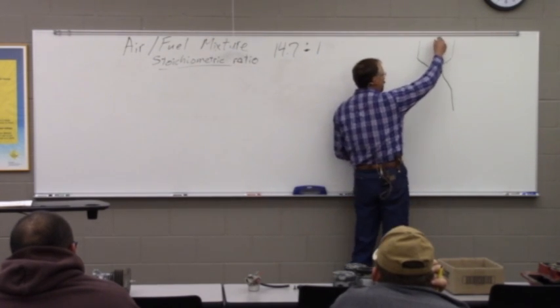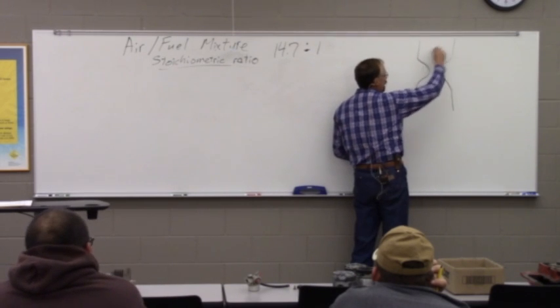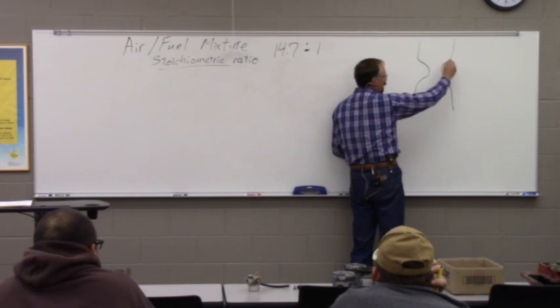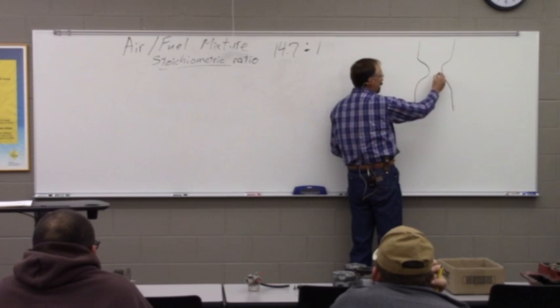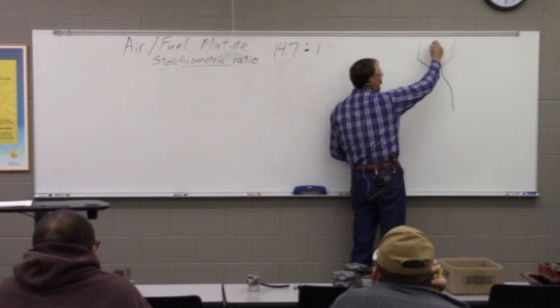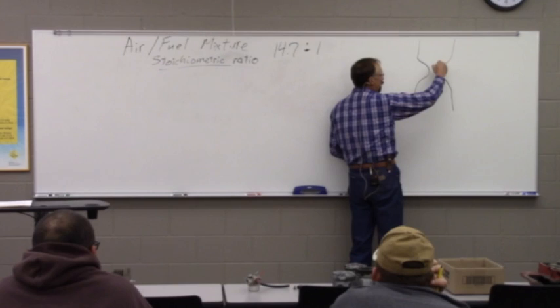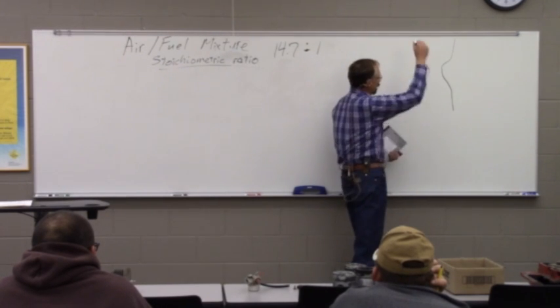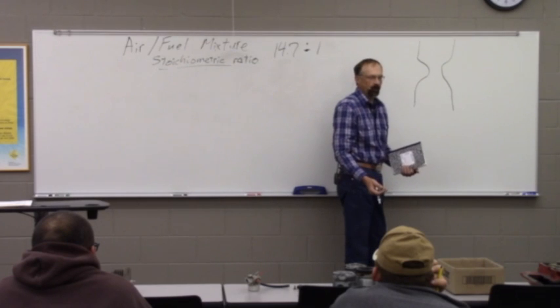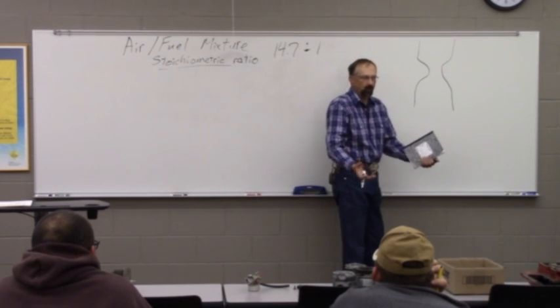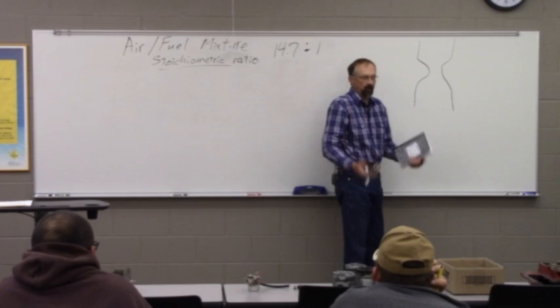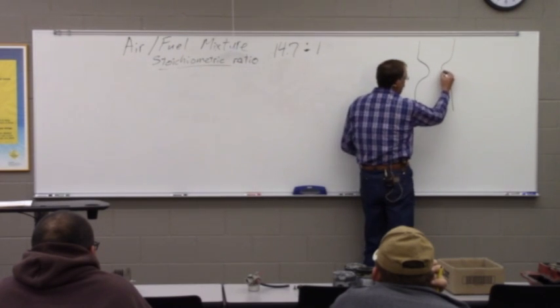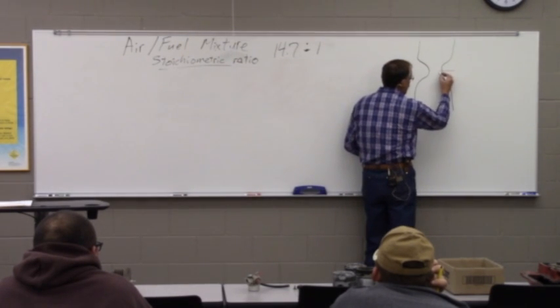But when you speed the air up, so if we've got air coming through a pipe that's this big, and then we choke the pipe down to this size, well, obviously for the air to go through this smaller pipe, it's got to go faster, right? Well, when it goes faster, the pressure decreases. In other words, it creates vacuum or a sucking action. So if we put a little branch here in the side of it,